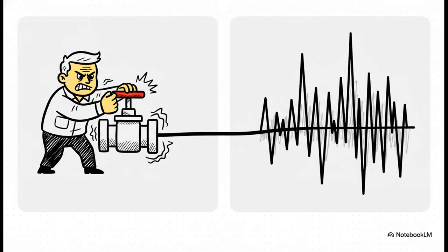And the real danger here is human psychology, right? If an operator gets impatient during that 40-second flat start and decides to aggressively tune the controller, maybe cranking up the gain because they think the process just isn't responding, they are setting a massive trap. Because the moment that delayed, high-order reaction finally hits, all that aggressive control action will violently overcorrect, and you'll get massive oscillations. You simply cannot tune a high-order loop like it's a fast first-order loop.